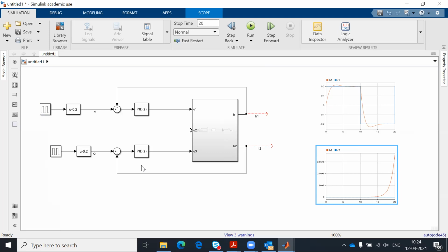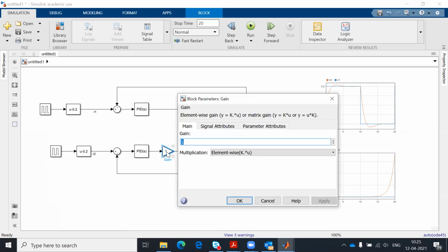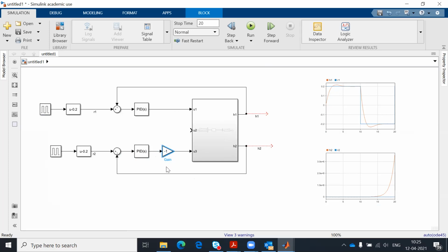It should be the inverse of the signal. Yeah, exactly. If you multiply it, for example, by -1, I like to have this gain here separately from the PI. It could be inside the PI, but to emphasize that, I want to have it here. I'm not trying to fine tune the controller, because we can do that and make it work better, with less overshoot, for example, and faster response. It's not the focus of our work here. The focus is to design two controllers. Now we have designed them, so we are able to control the second one as well.